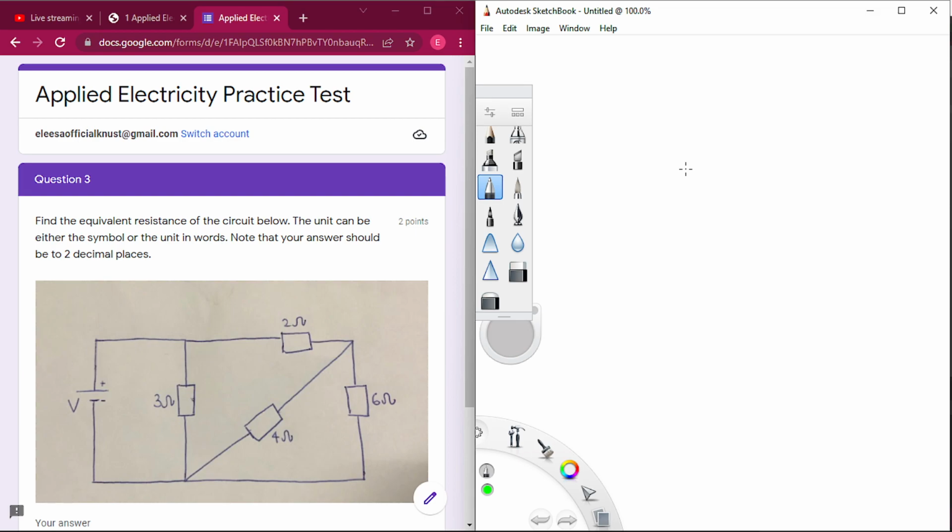resistor. So just like in the previous one, we can now easily identify that the 4 ohm and then the 6 ohm resistors are parallel connected. So that's a 6 parallel 4. Now 6 by 4 over 6 plus 4, which equals 2.4 ohm. So we can now draw a simplified circuit, right? This still here, and then this still here. This now becomes just 1, whose value is now 2.4.